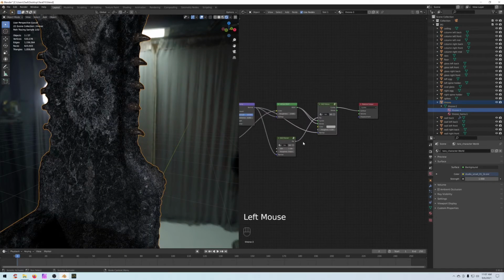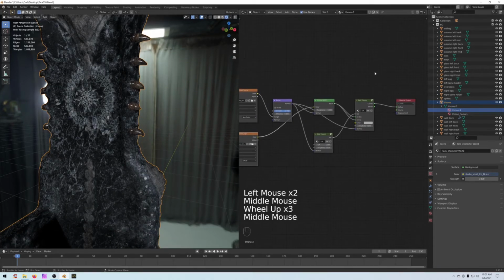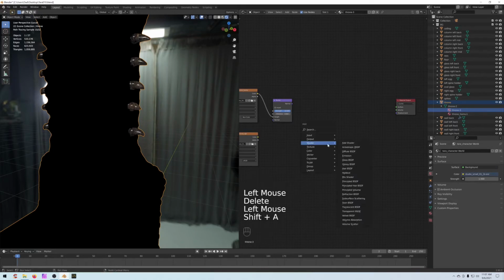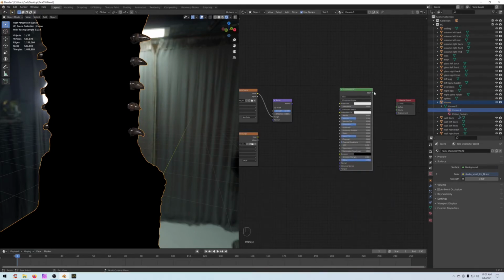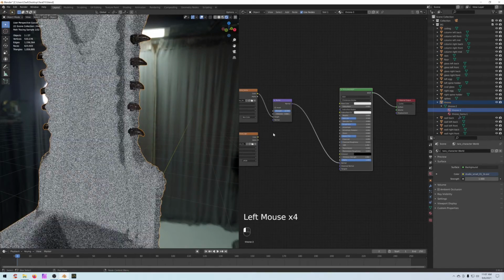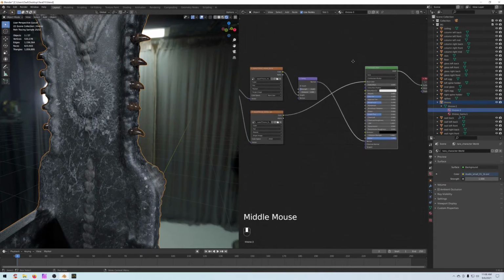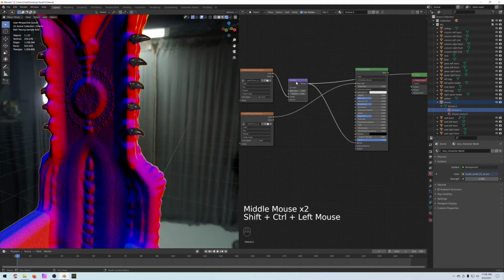And the stone has 2 maps, bump and RGB. So we will put in our principal bsdf. We know the bump goes into the bump, and the diffuse goes into the base color. Set this to 0.1 and 1 because that's what works for me. Looks pretty good in the reflections here. You can see the bump showing up. And if we isolate it, that's a Control-Shift click, we can see the bump in the material. That looks pretty good. We'll take that.